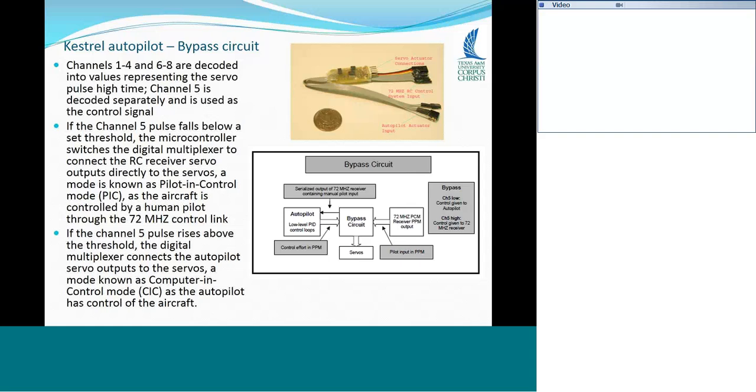And basically, there's a button on that manual control unit. You push that button, and that's what sends the signal low and says, okay, now I'm taking manual control, and then you fly it using the joysticks, whatever. Then later on you either push a button on the manual control or you do something in the autopilot. It may vary from one system to the other. I think in the Piccolo, you actually do something in the software, in the laptop, to say, okay, I'm going to take control again. I don't remember for certain right at the moment. And I think it varies from system to system.